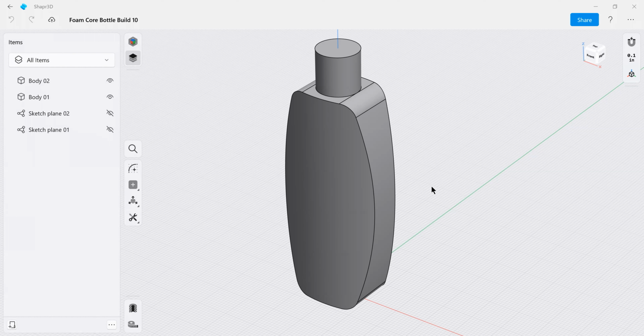So by curving this surface out, we can control that flexibility and we can make it easier to label and prevent this paneling effect. Now, paneling can also happen in the other direction where the panels can bend in and suck in. That depends on atmospheric pressure from whatever the material is on the inside and the outside. And again, it doesn't look very nice and it looks like there's something wrong. So that's another feature of curving these panels front and back. It's very typical. We're going to see a lot of that in bottle design. So I'm incorporating that in this particular one.